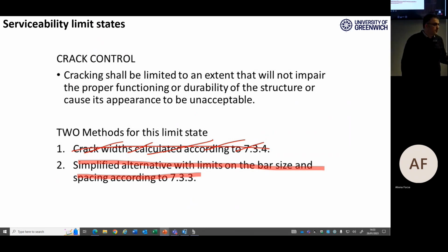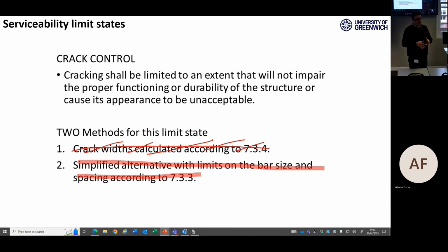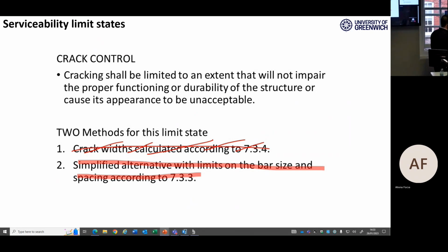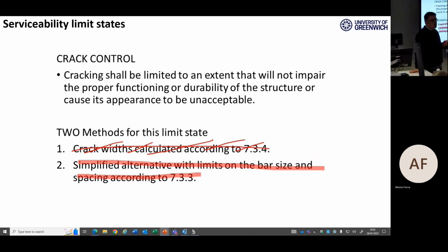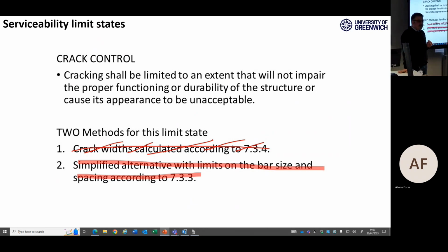And you know the concrete material is supposed to crack because the tension part will crack very soon before it goes to its ultimate limit state. And you always have cracks in your concrete. So the problem is that you need to comply with some regulation to ensure that the crack is acceptable, is small enough. Okay.